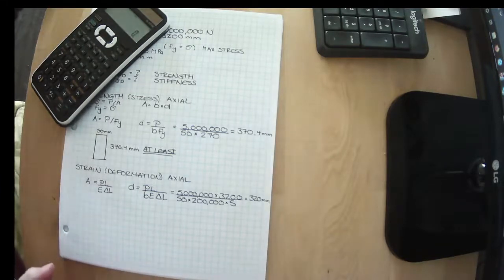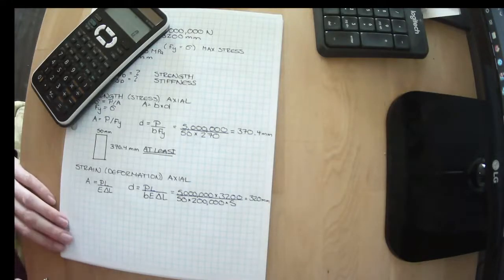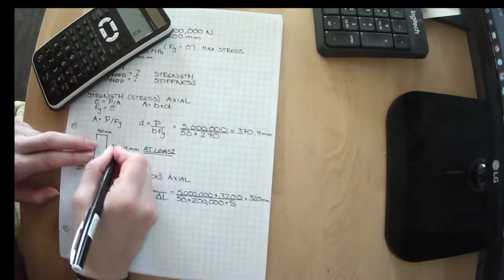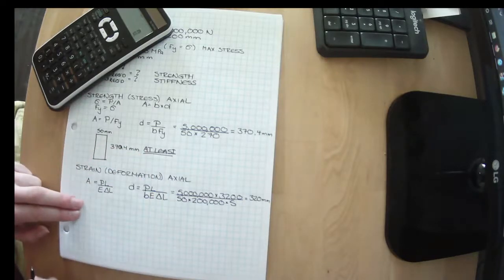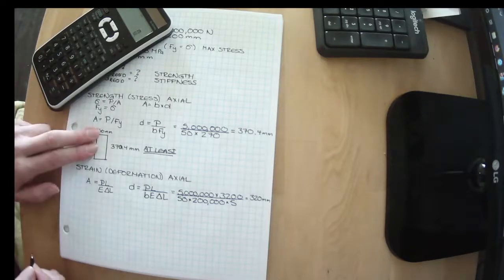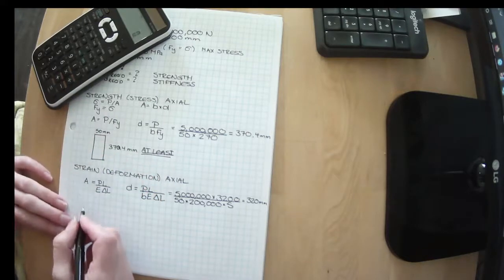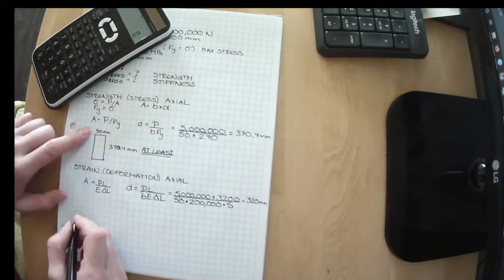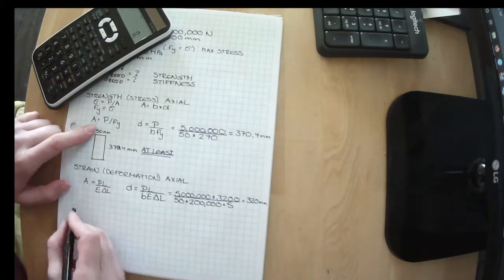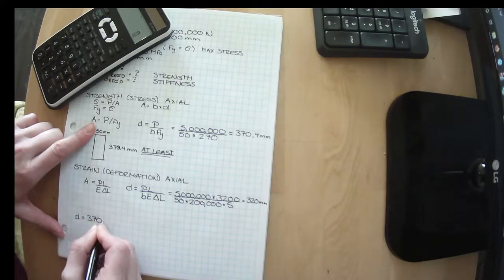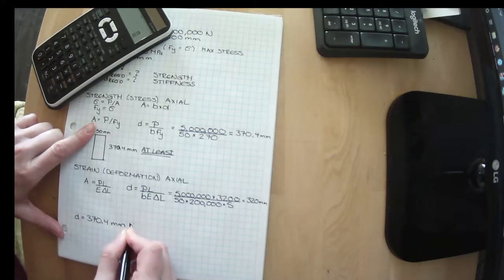So the question is, what size do we need? Well, if we need for strength at least 370.4, and for axial we need at least 320, it seems like this is the one that governs, and for both of these criteria to work, we need a member that is 370.4 millimeters minimum. So D needs to be 370.4 millimeters